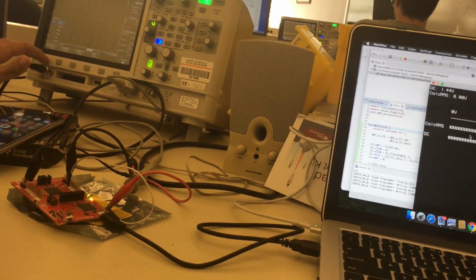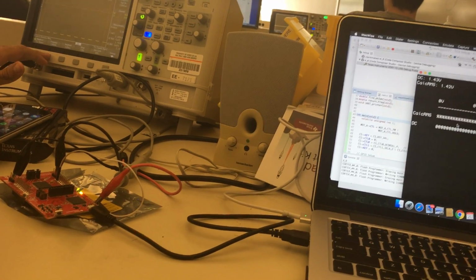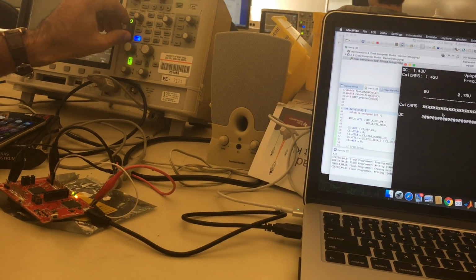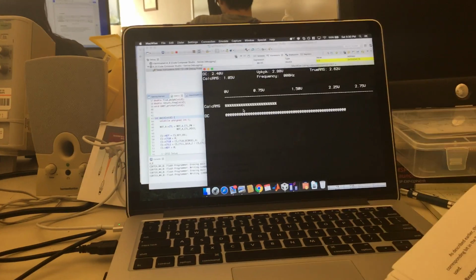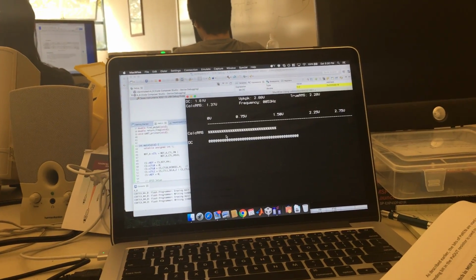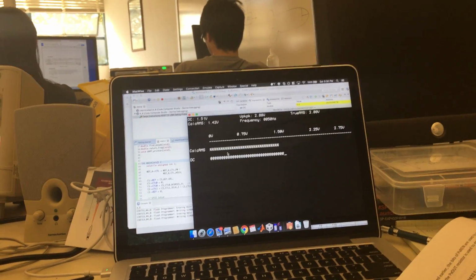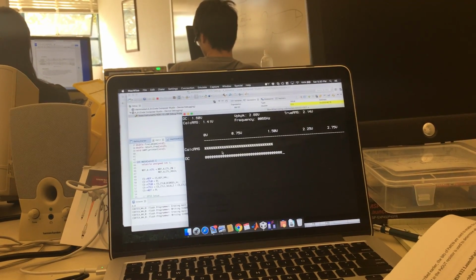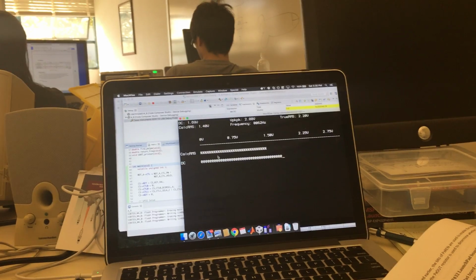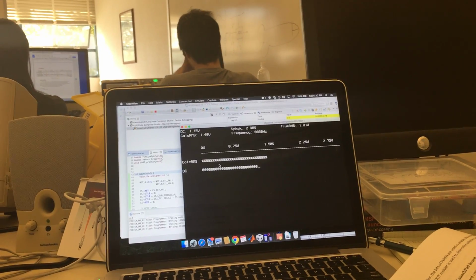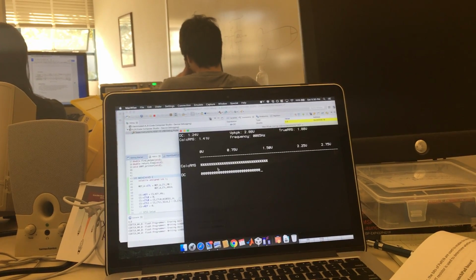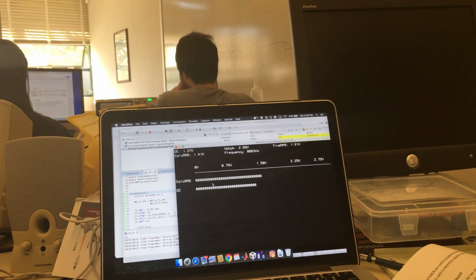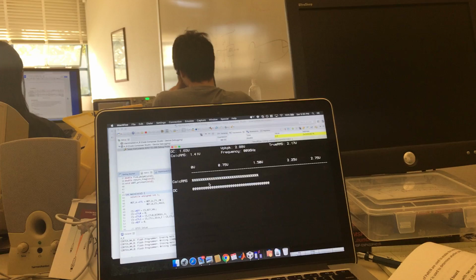Lastly, we're going to change to a square wave of our best frequency, which should be around 50 hertz or so. 3 peak to peak, 1.5 offset. At this point, you can see it hovering around 50, but then sometimes it skips. We can increase it again to have the most stable one, but below 50 doesn't really work. If we go to 100, pretty stable.